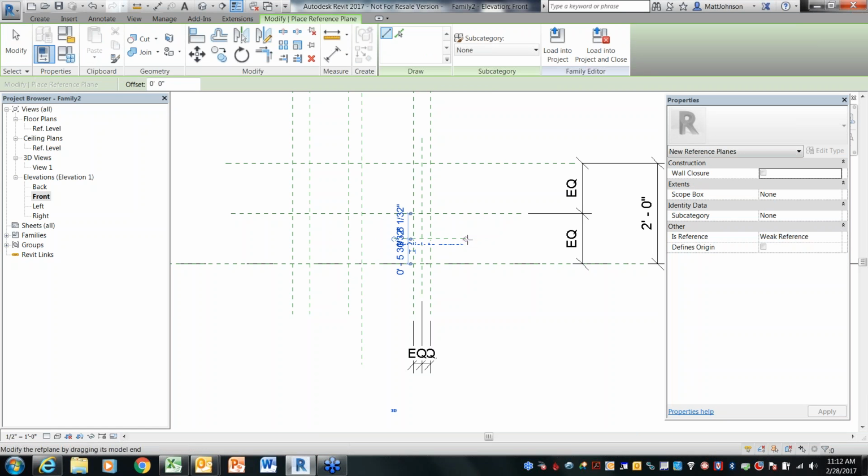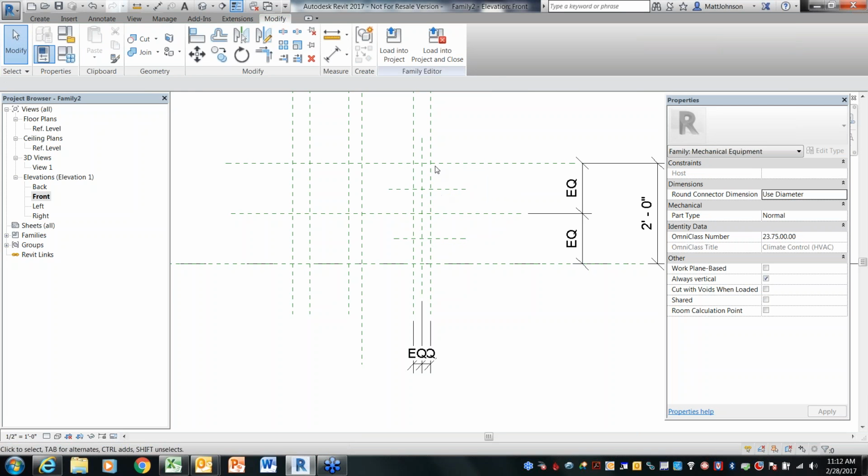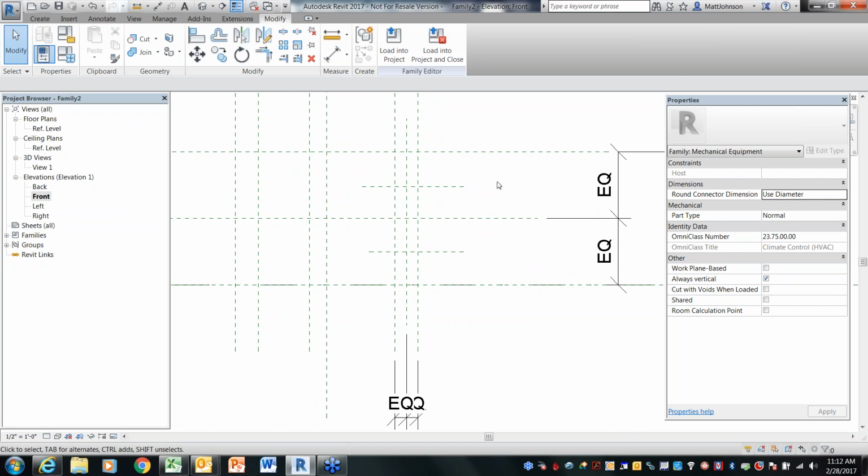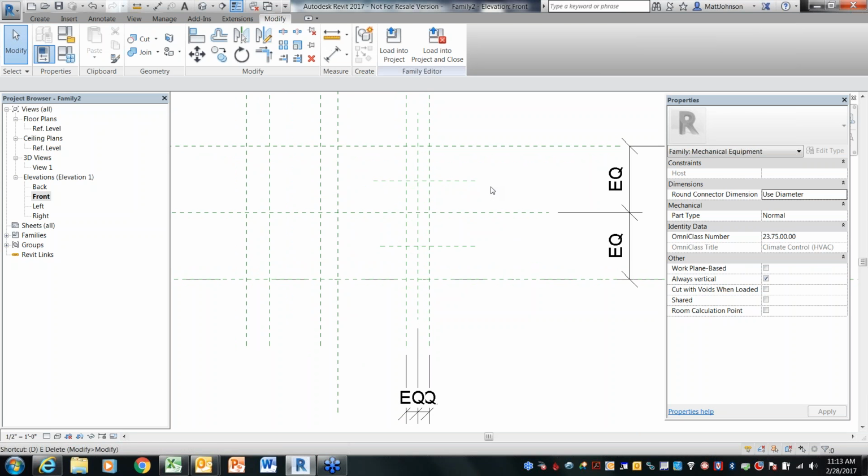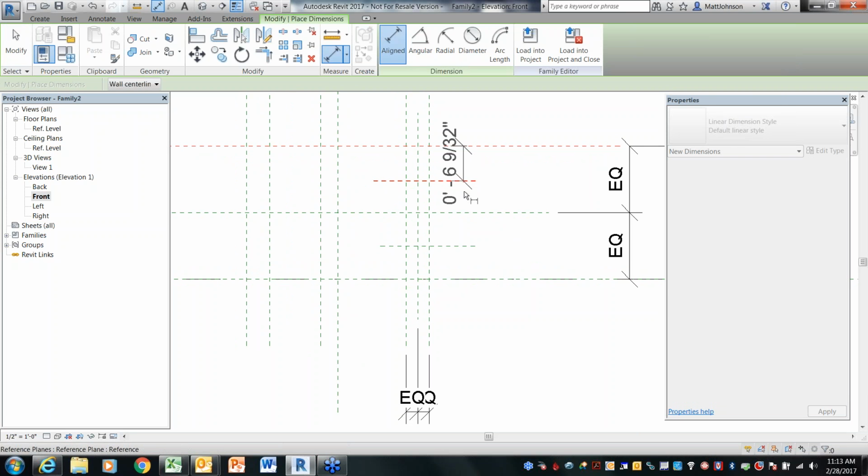So usually we'll just make this one to where both of these pieces of pipe are always going to stay, like if our box flexes up, we always want this pipe to stay in the center of each quadrant or each section of the height of the box here. So what we're going to do is just put that same equal distance constraint there so they always stay center. Right? The distance doesn't matter.